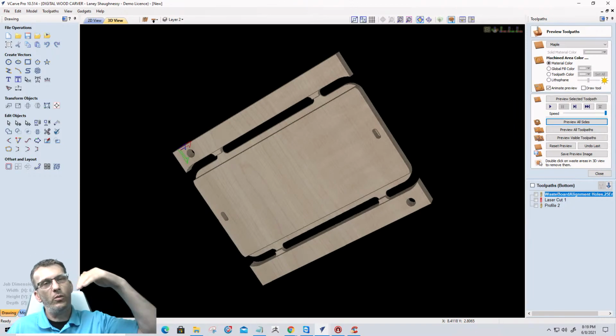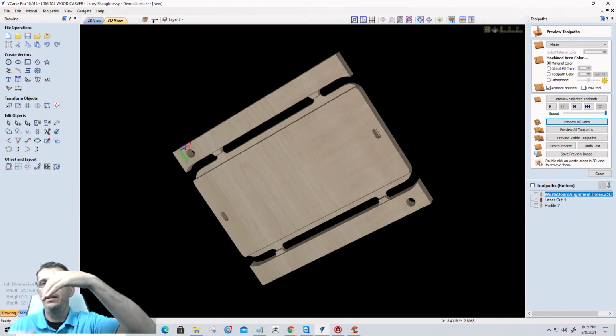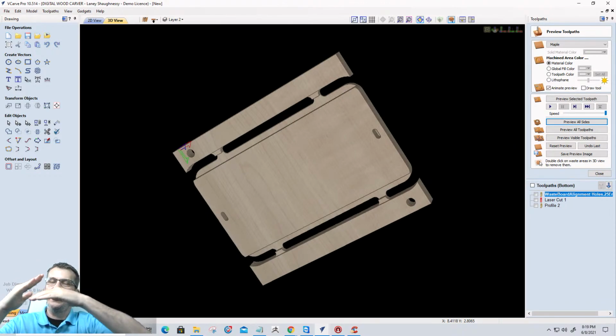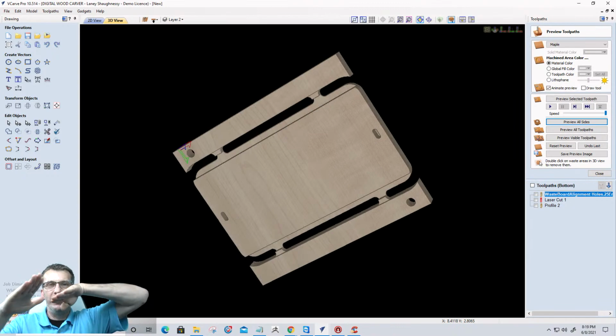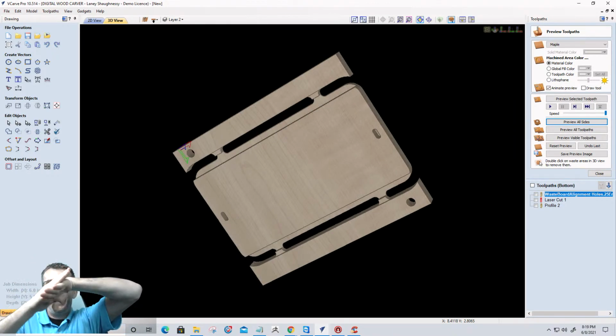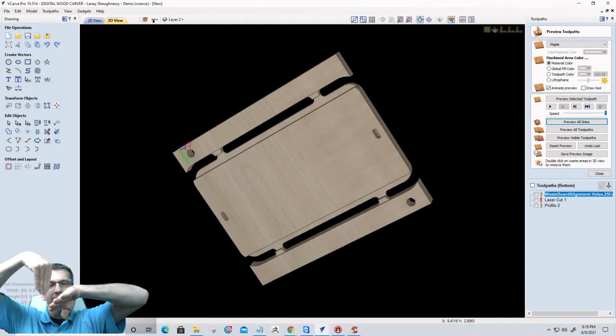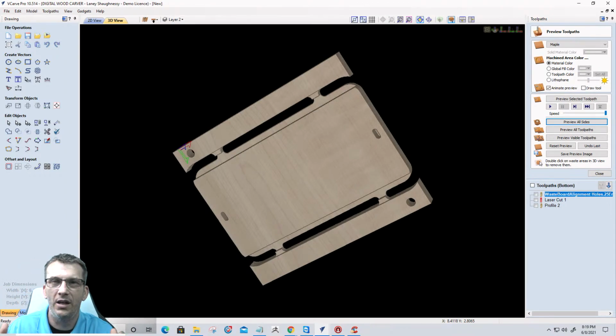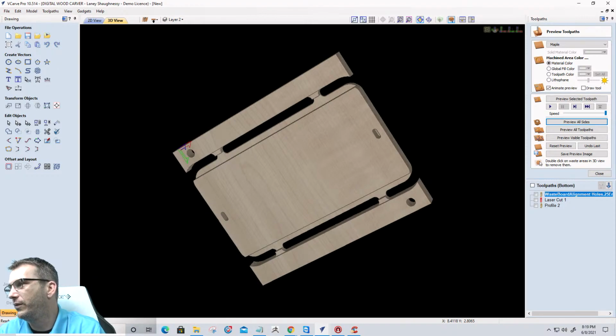You just have to make sure whatever dovetail bit you're using on the base to cut that undercut where the lid's going to slide into it. Your chamfer on your lid has to match that dovetail, and your dovetail bit doesn't cut like that, right? So we can't cut the lid with the dovetail bit. We're going to have to do it with a chamfer bit or a V-bit or something. So Jonathan, hopefully that answered your question. But yes, it is doable.